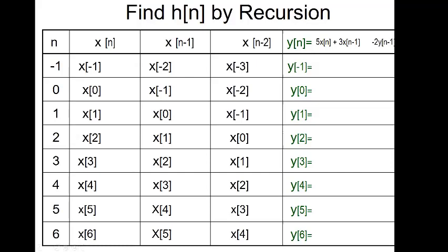In the first column, the x sub n column, we'll put in the values of a unit sample sequence. Well, a unit sample sequence is 0 everywhere, except at n equals 0, it has a single 1 value. So that's pretty easy. So 0, 1, and all zeros after that. And go ahead and fill that in your table. X sub n minus 1 should look like exactly that same column, but everything is shifted down one row.